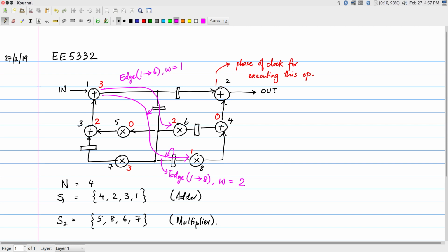Both of these delay elements correspond to this magenta edge that I have drawn over here. I have drawn it in this fashion so that it is compact and easy to visualize what the structure looks like. But to interpret which edges need implementations when you fold the architecture, you need to take the operational nodes, the adders and additions, and the multiplications, and find the connections between them directly: how many sample delays are on those edges between them.